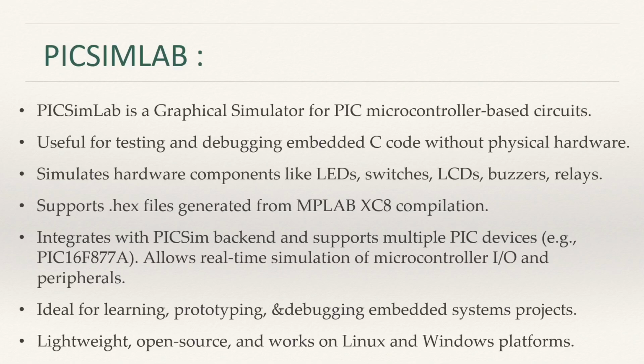Integrates with PICsim backend and supports multiple PIC devices, for example PIC16F877A. It allows real-time simulation of microcontroller input and output and peripherals. Ideal for learning, prototyping and debugging embedded systems projects. It is lightweight, open source and works on Linux and Windows platforms also.